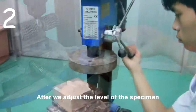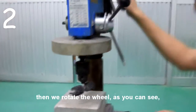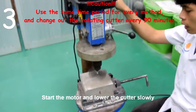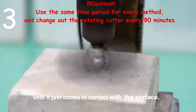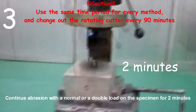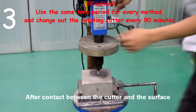After we adjust the level of the specimen, then we rotate the wheel, as you can see, to contact with the surface of the specimen, as you can see in the video. Start the motor and lower the cutter slowly until it just contacts the surface. Continue abrasion with the normal or double load on the specimen for 2 minutes after contact between the cutter and the surface.